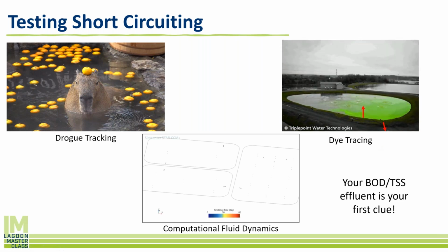You can also get dye with rhodamine in it. Essentially, it's a chemical compound that can be detected to extremely low levels. So it can be put in at the influent and then tested with a sensor on the effluent to find out what concentrations of dye are showing up and over what intervals. And they'll give you a sense of short circuiting, how much, and when.